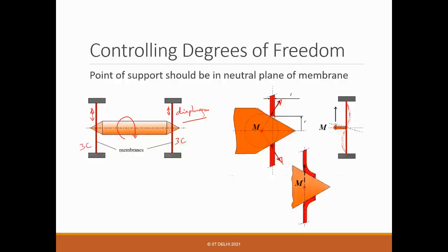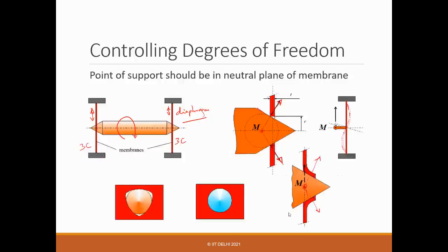So you just make a contoured surface here to support it. So it will be something like this now, right? So the forces will be here, and the equivalent point M is now shifted, and it will lie on the plane. And now it is solved. Again, you can't make a very precise hole, so in that case you just make a triangular hole and you insert it and it will stay there. You don't have to make a precise circle.